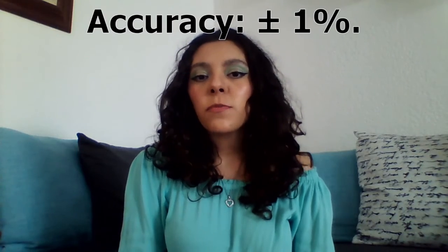The pipe must be clear of obstructions near the inlet for the measurement to be correct. It requires minimum 15 diameters of a straight pipe upstream and 5 downstream. Like the swirl method, it must be installed perfectly flush with the pipe to ensure proper vortex formation. The vortex must be installed so that it is always full of liquid. Its accuracy is plus/minus 1%.